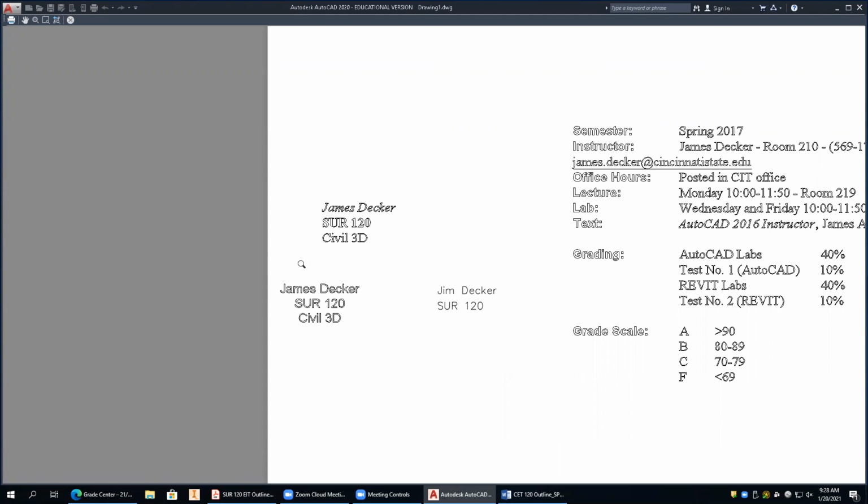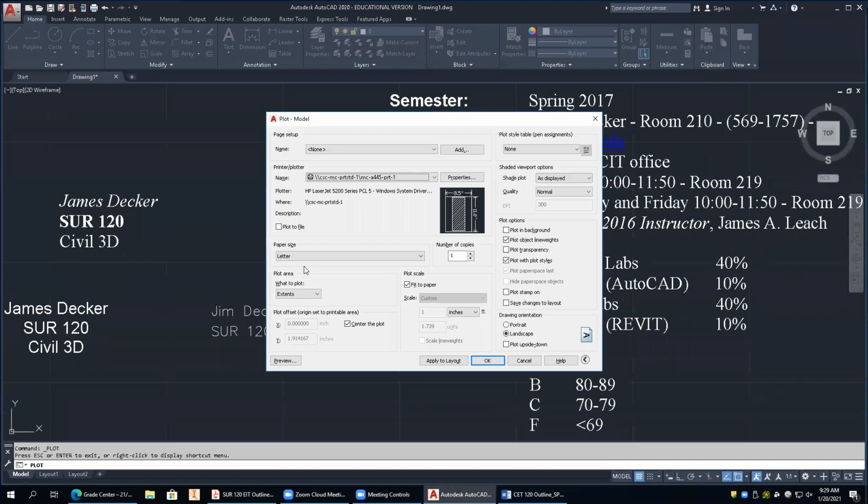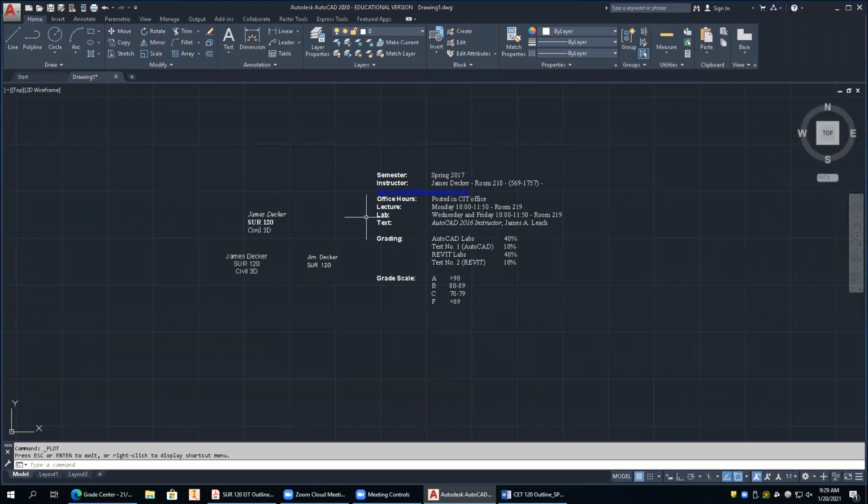And like I said, it doesn't show up on the screen that way. Okay? So it's not that huge of a deal, but some people will use that sometimes for different purposes. The other thing is too, it's across the board, so I can't have some text filled and some not. Okay? So we're going to go ahead and cancel out of there. Let's go back into the text fill system variable and set it back to 1. Okay? Because we don't want to mess that up.